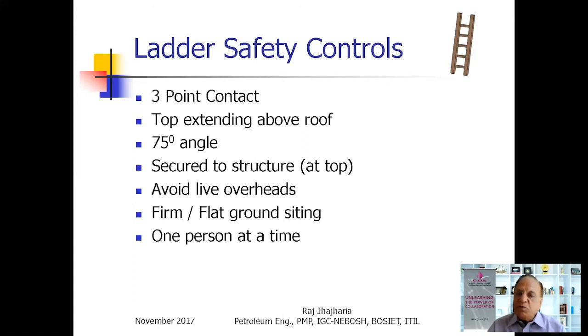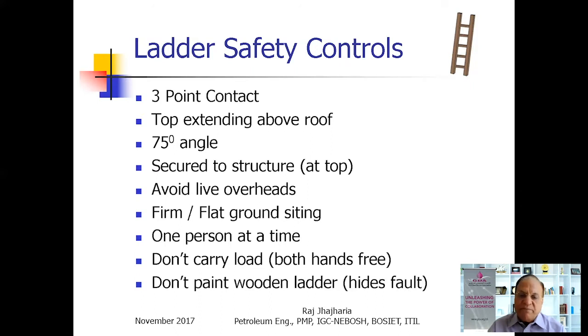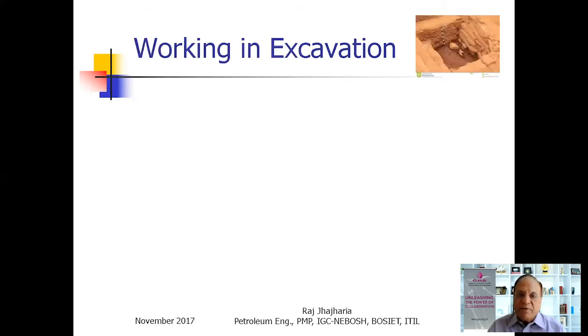And only one person should climb the ladder at a time. And while climbing the ladder, never carry any load. Why? Because you want to maintain 3-point contact. And for that, you need to have both hands free. And don't paint the wooden ladder. If it's a wooden ladder, do not ever paint it. Why? Because if you paint, the hidden faults of the ladder, breaks and cracks, will be hidden. So you will never know whether it is a good quality ladder.